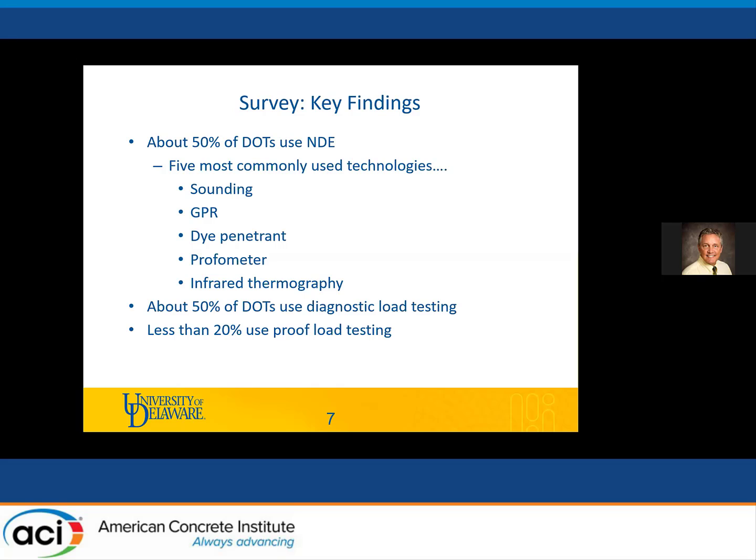We also found that about half of the DOTs are doing some kind of diagnostic load testing, but a little less than 20% are doing proof load testing. If you're not familiar with the distinction between those types of tests, a diagnostic test is conducted with loads generally below the design loads, below the legal loads, and it's primarily conducted to determine things like load distribution factors, bearing fixity, the effects of secondary members, things like that. Those results then feed into an analysis or a model of the bridge to calibrate it,